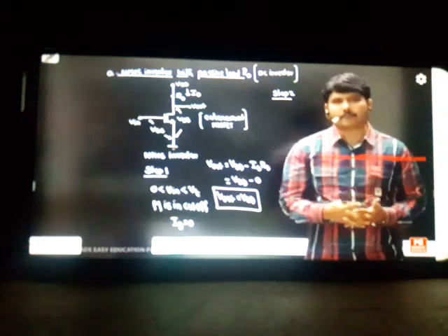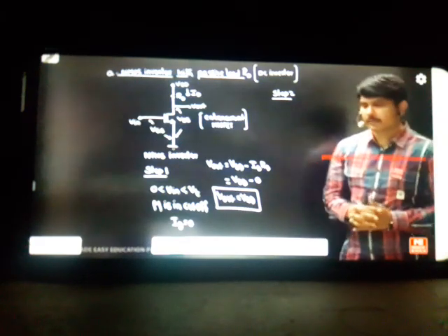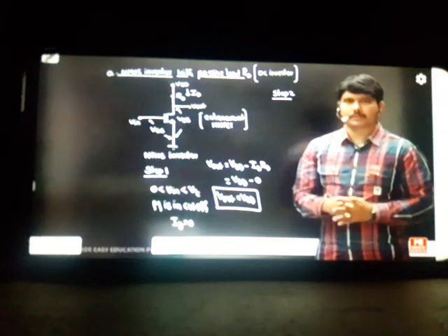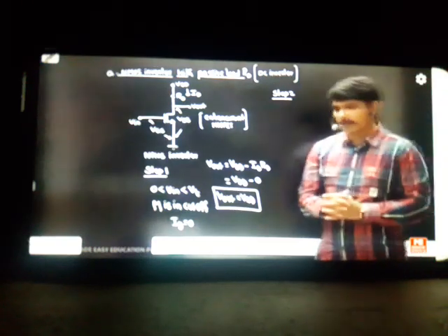How can you answer the question like that here? M is off means cut off, or on, you are asking. Off means cut off. On means it will be going in ohmic region or triode region; we call it as on. When you are in active region, we call it current saturation. We are just replicating points to understand. So off means cut off, my friend.